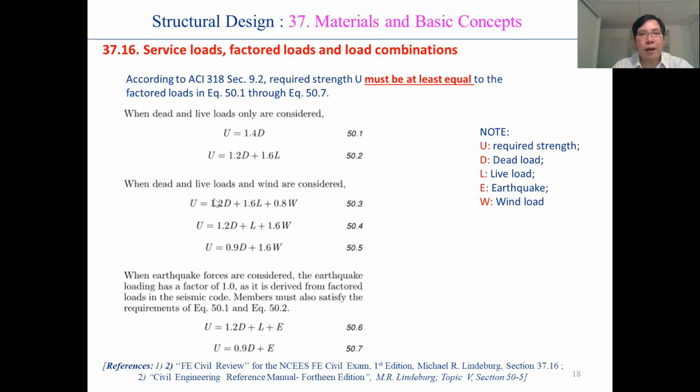And when the dead and live load and wind are considered, you can apply the equation. And finally, when earthquake forces are considered, you can apply the equation. You know that Q is the required strength, D is the dead load, L is the live load, E is the earthquake, and W is the wind load.